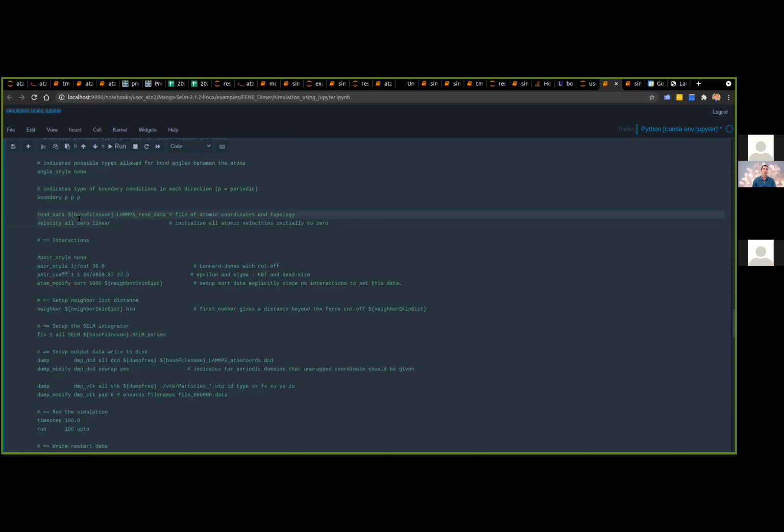This is really an important line here. This is going to read in all of the configuration information. And so it's a little funny. We're doing everything in Python, but there will be a configuration file that I'll have the Python script write out as a kind of meta piece of data that LAMMPS will read in. There are things that might be ideal to do through a function call, but I found it's more convenient to write a little temporary configuration file, which provides a smoother way of getting LAMMPS to operate and move forward.